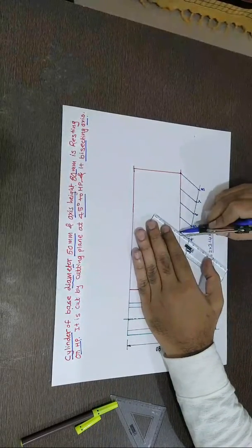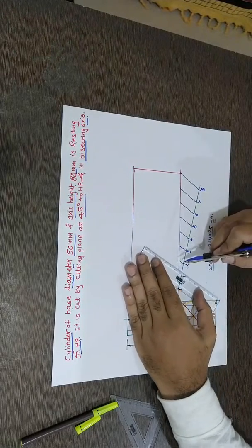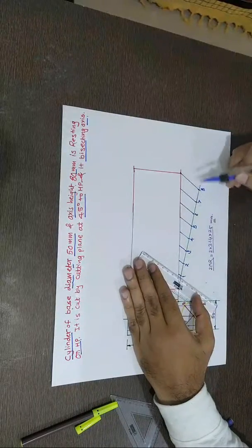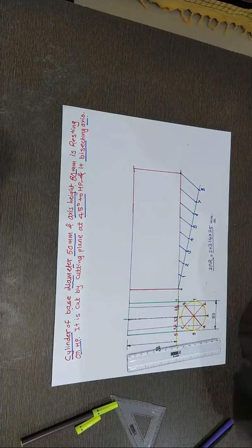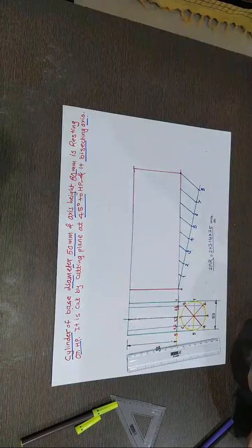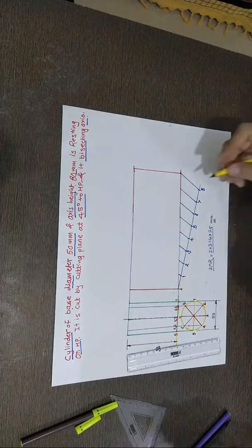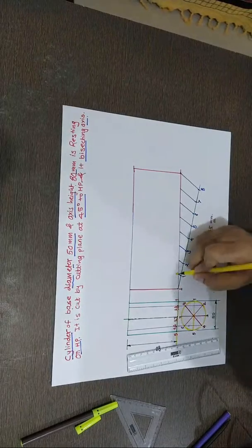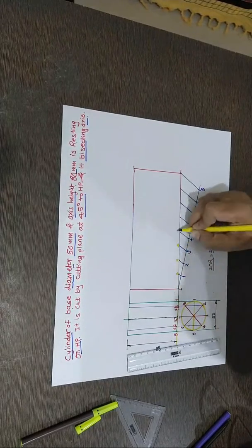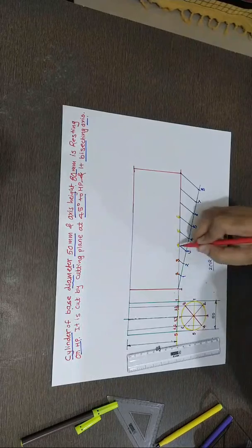Excuse me for this because I don't have a drafter with me right now or any other instrument. Just keep in mind all these lines are parallel to each other and the reference line is this last end joined with this end. Okay, fine, this is looking quite parallel. Now draw a line passing through these ends. So now this is 1 because I'm taking here 1. Okay, 2, 3, 4, 5 and so on. I'll use a color which is quite visible.